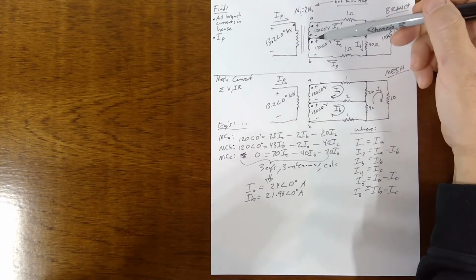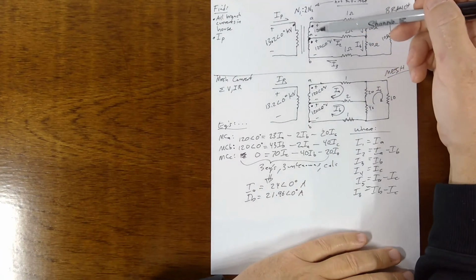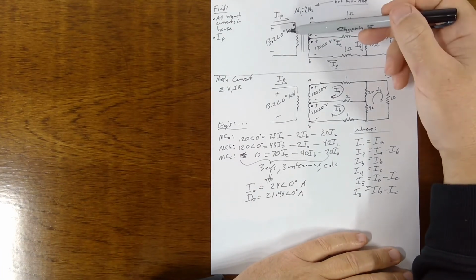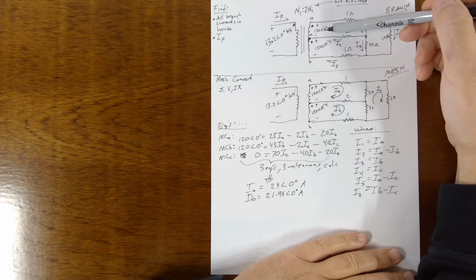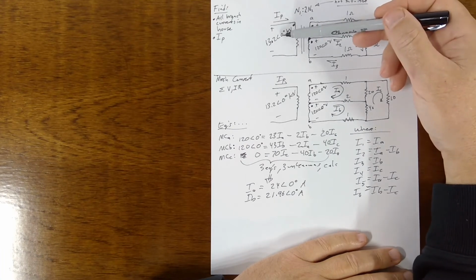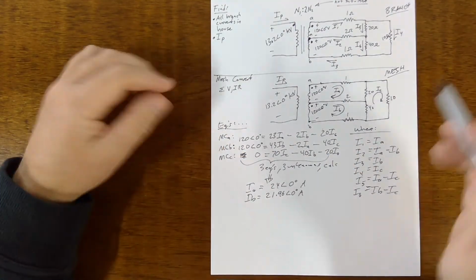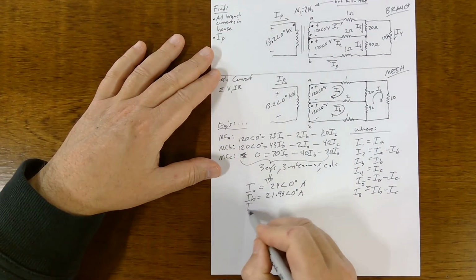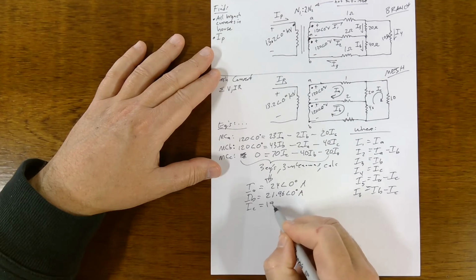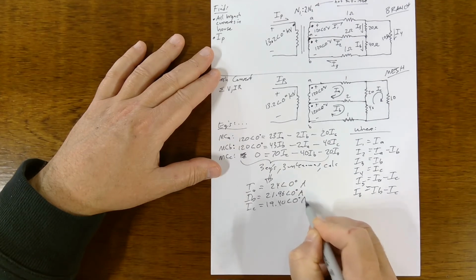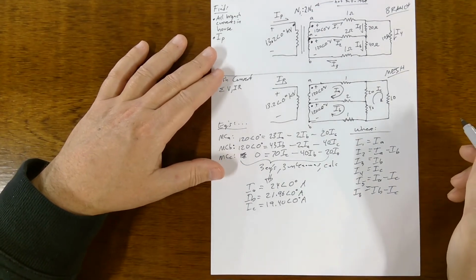The voltage will be in phase, because these voltages here are being generated off of this guy. They're going to be the same phase. So if this is 0, it's just an arbitrary reference starting point, then these will also be 0. So I feel better. Anyway, calculator tells me 19.40 angle 0. These are the 3 dudes.